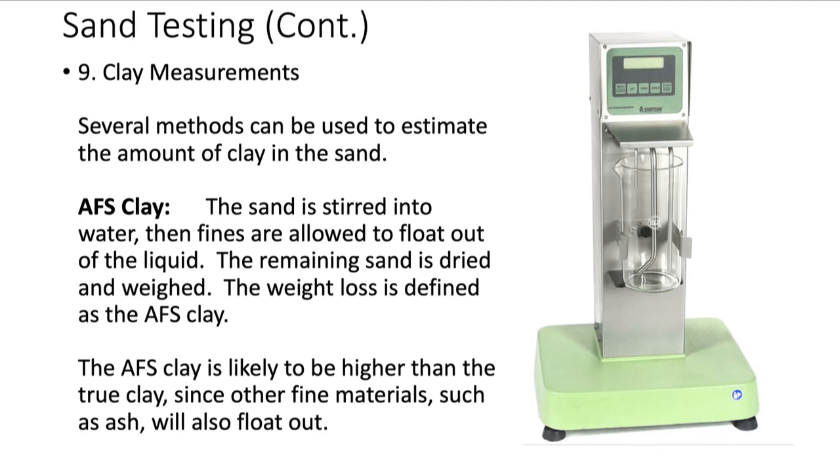So how do we measure the clay content? Well, the clay is measured two ways. One is we can get the total amount of clay that's in the sand by, remember earlier I said that the platelets always stay suspended in the liquid. So we have this little thing here, and what it does is it takes your dried sample, and by the way, you're gonna take your dried sample and weigh it, and then you're gonna put it into this beaker.